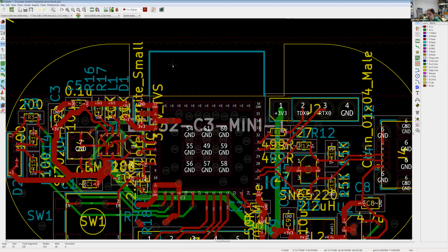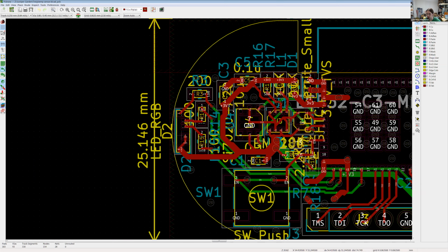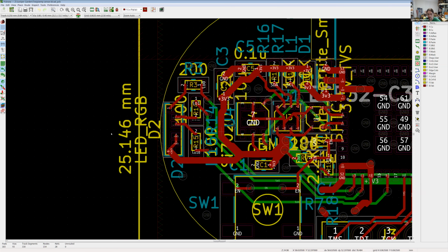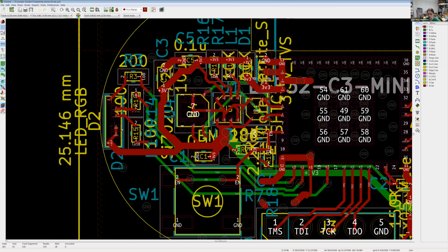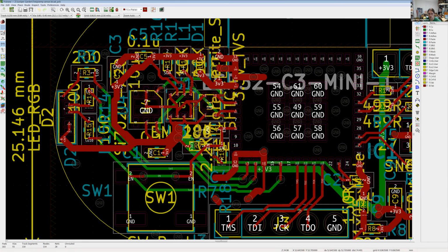And so we got the LED packaged on the bottom here, and it's just an RGB LED. The way it works is that the voltage is sunk to ground through the I/O pins, and so it goes through the resistor, and that's how you turn it on. It's got 3 volts across it through the resistor, and then these I/O pins here just sink it to ground.